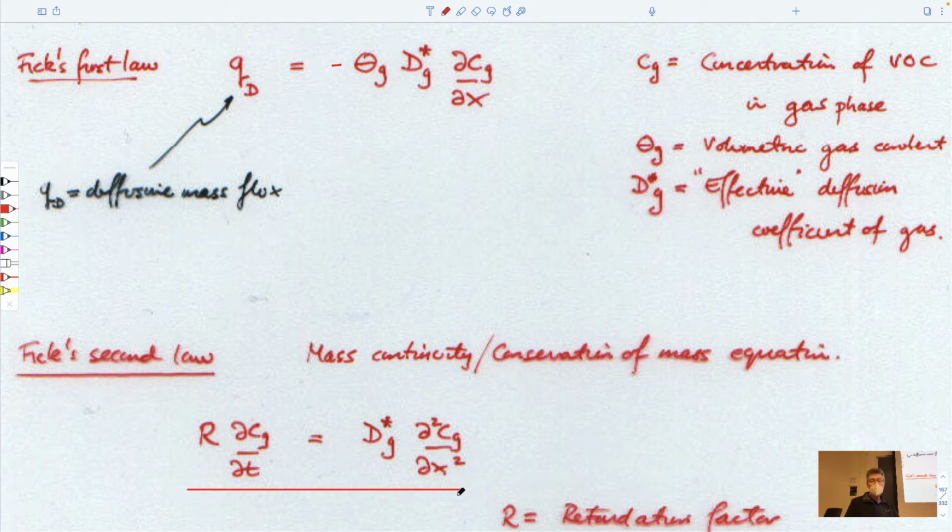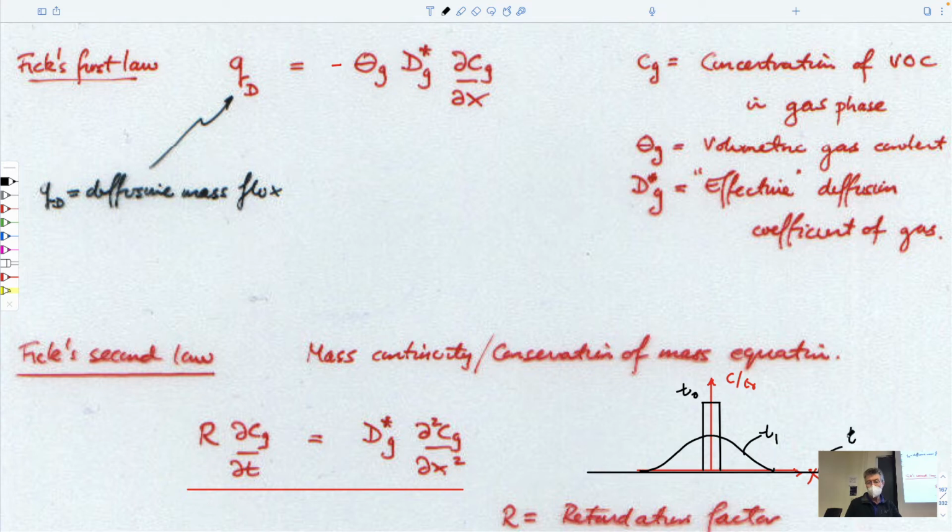And so this is the expression that we'll use to define diffusion in the system. It's not any different from the system that we looked at before, which you might remember had we explained behavior in terms of length, or radius if you like, and concentration. Perhaps I should change it into a different color. And if you start off with concentration of a drop of ink, if you like, in milk, maybe that was the analog that I mentioned, at time t0, it might look like this. At time t1, it looks like this. And time t infinity, it looks like this. And this is just the normal, the Gaussian distribution curve, the normal probability distribution happens to be.